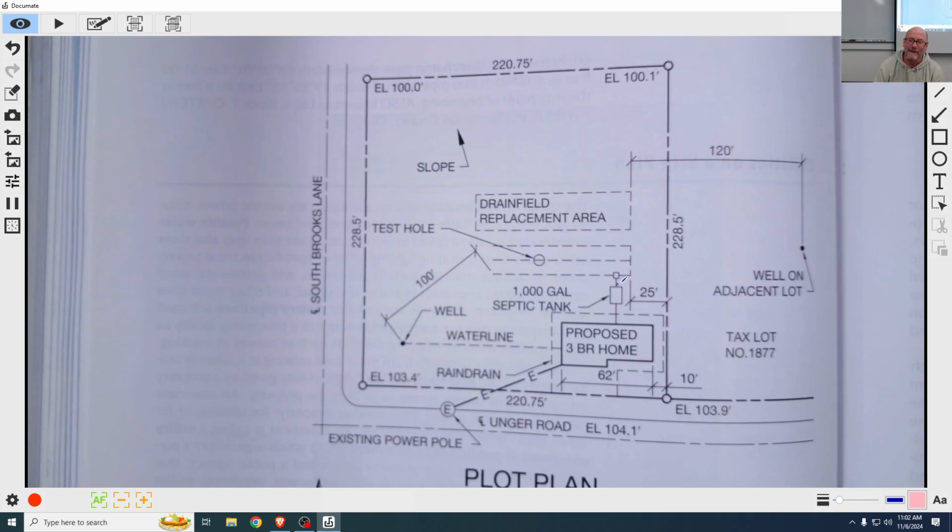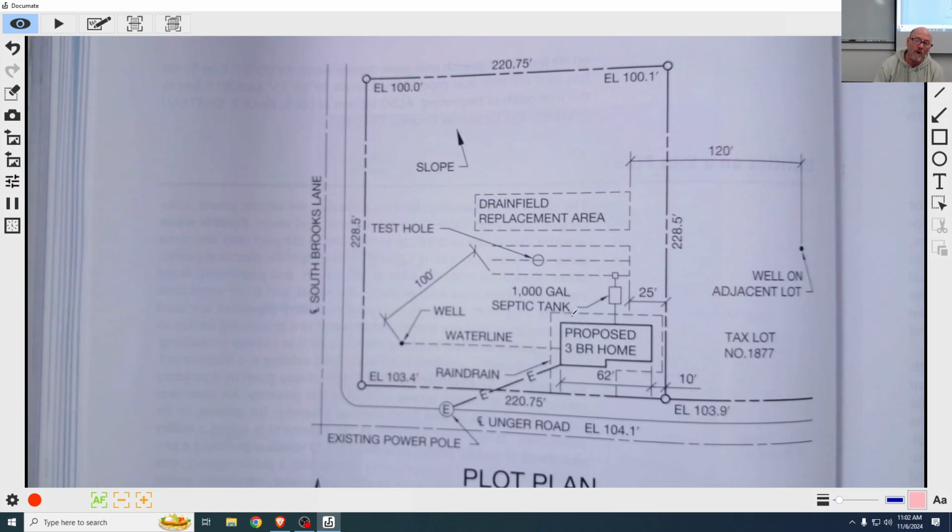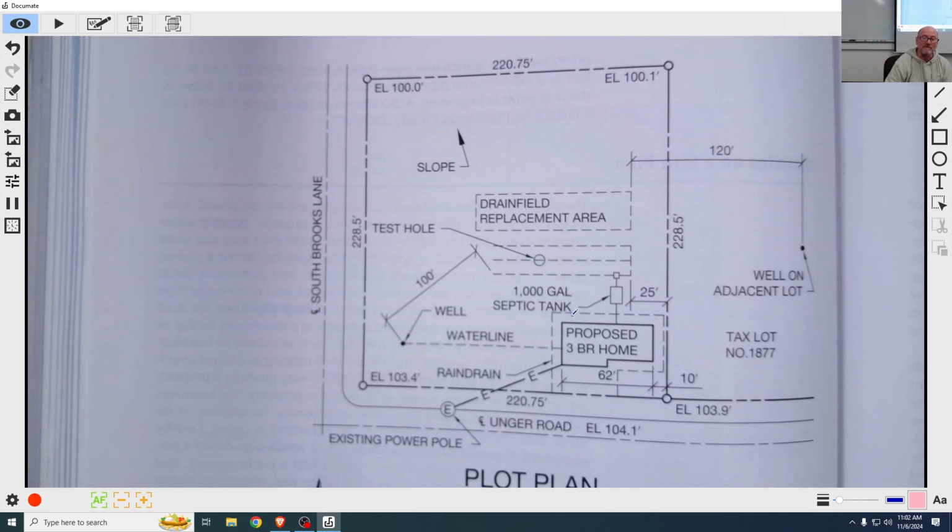But anyway, the water in between, basically the stuff that can get filtered through the ground, goes out into a leach field. A leach field is just perforated pipe separated by a specific amount, usually like 10 feet. They're parallel pipes, however many are needed for the size of the tank or the size of the house.